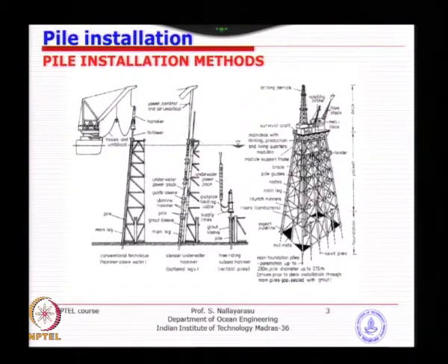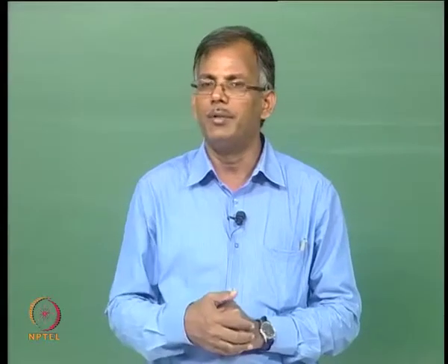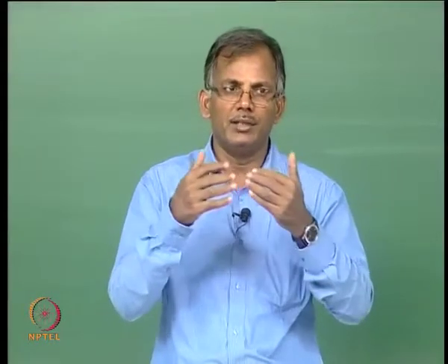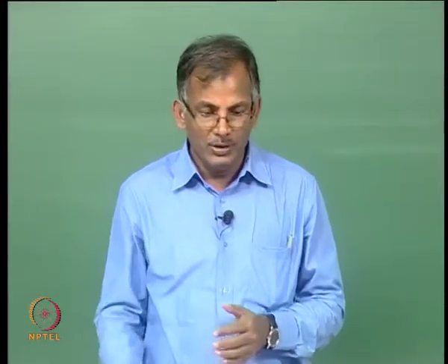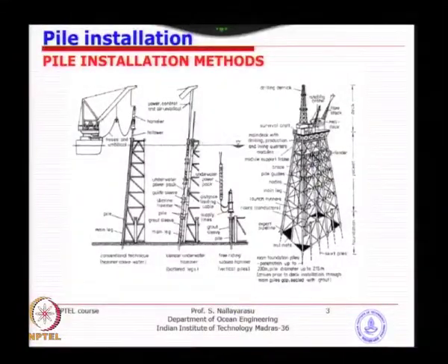You do this estimate, you find out the strength of the soil. You have been given a borehole report. I think by this time you already have an idea what undrained shear strength is available, or angle of internal friction. Using those values and the weight of the pile, you can find out when the pile will stop, because you know how to calculate the bearing capacity for a tubular pile section.